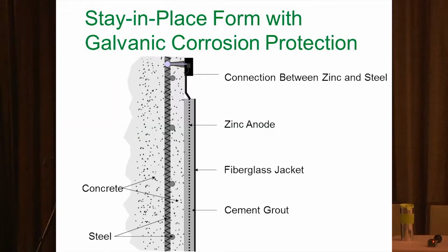And what you'll see here is there's typically a jacket on the outside, but these are encapsulated within that grout or the concrete. And now what you're able to do is provide that same current that we were looking at. It's basically the same concept as those little point anodes or those puck anodes, but it's just done on a greater scale. But you can work in a very, very difficult environment and still get some terrific protection over a long period of time.